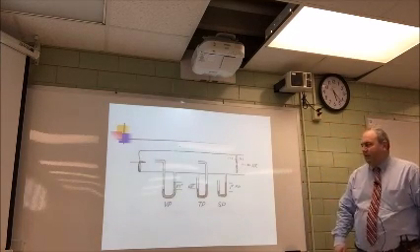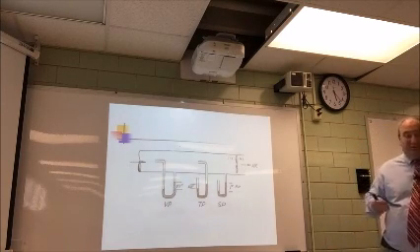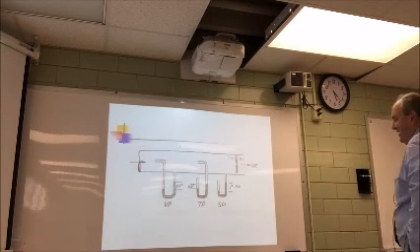So, what do you think's happening here with this one? Guys, I'm not an artist, so sorry about the bad diagrams, but it gets the point over. So on this side of the fan, what is it? And positive again. So what's the static pressure? 1 inch, right? Notice that's the difference. What's the total pressure? So what does the velocity pressure have to equal?